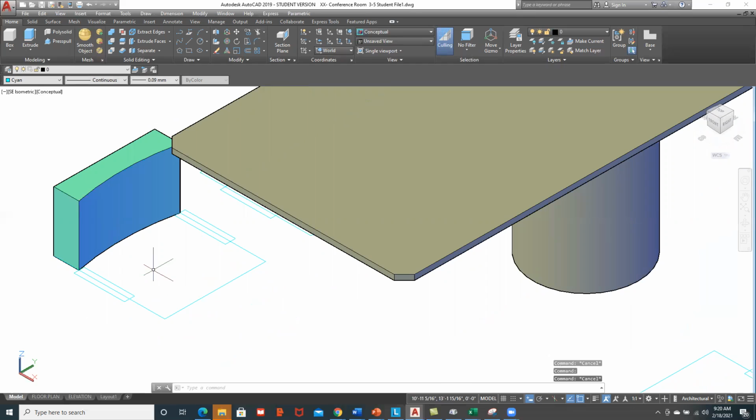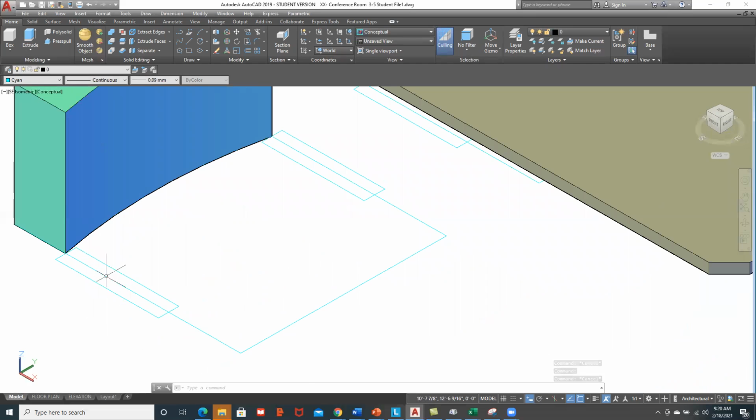And before I do the bottom of the chair, I think I'm going to do the sides. And so if we press pull this into a shape, and sometimes rather than press pull that, I'd be better off to join these because it'll grab this line. And so what I'm going to do is I'm going to region the shape for the armrests. And so to do that, I'll click on that. As long as the lines are endpoint to endpoint, it'll model it properly. So we'll hit enter. That looks great.